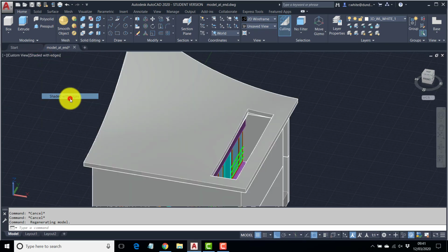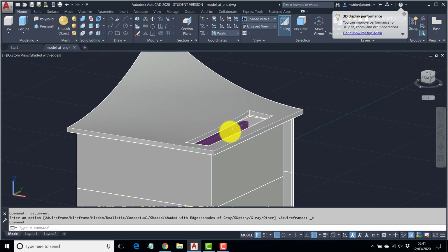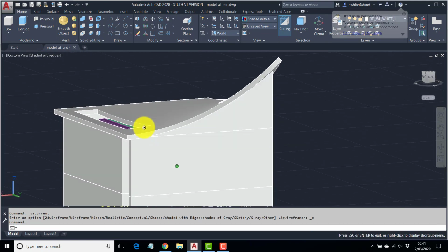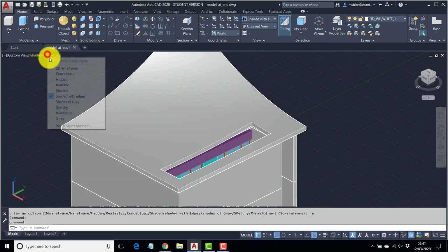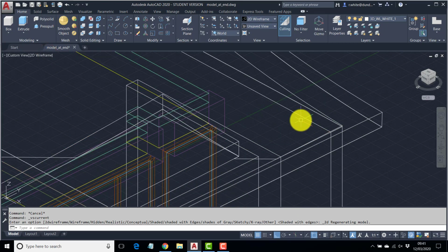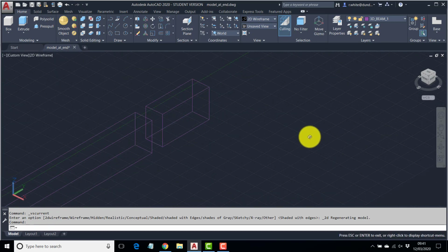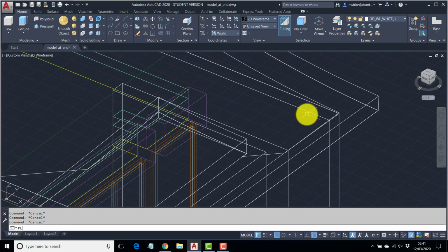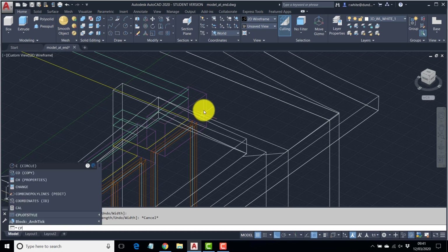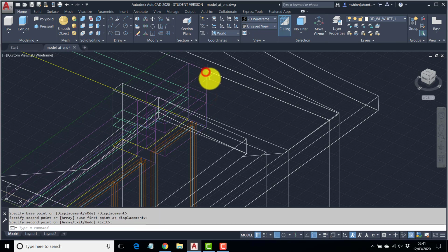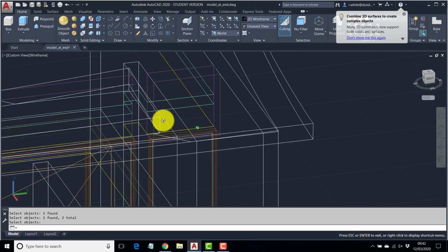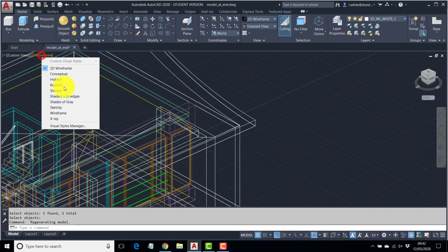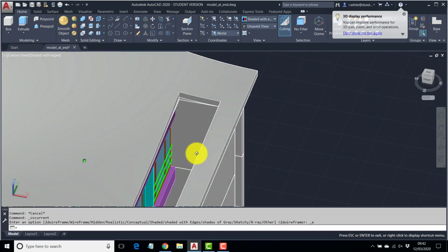Let's just have a little look. Now you can see there is a gap there that would need filled, and what we could do there is copy the beams up a bit higher. So let's just do that. The beams need copied and joined together at the height of the standard roof. So it's to there. Copy the beam and then union those two together, and that will close the gaps. So we shouldn't see any airspace now in there, but we've still got our light well.